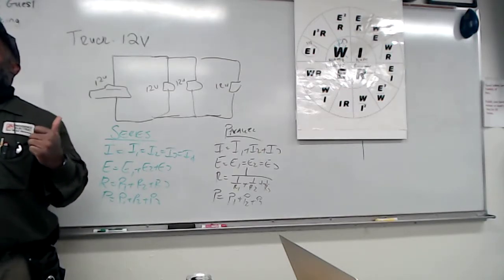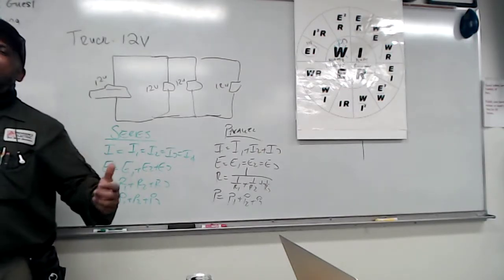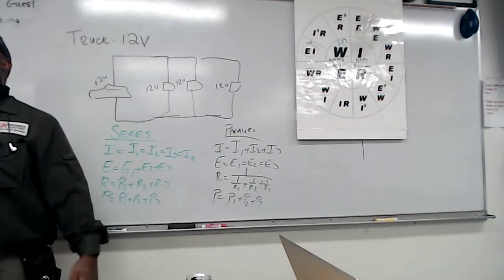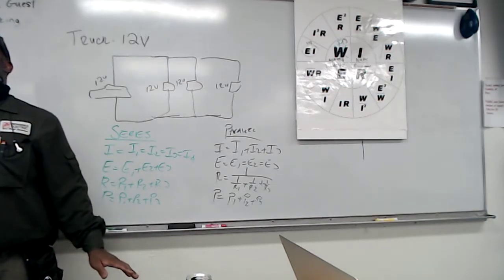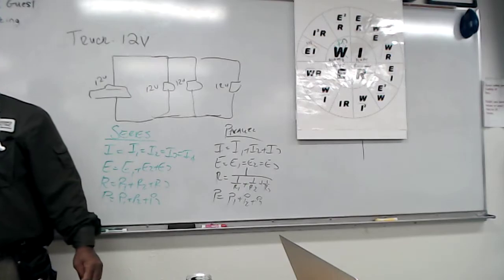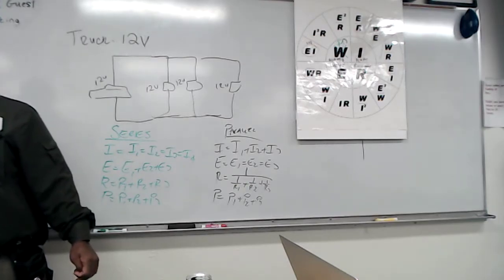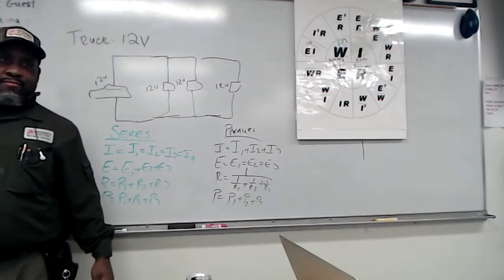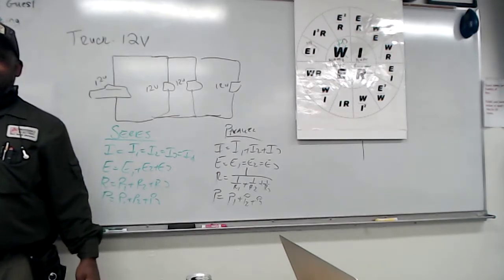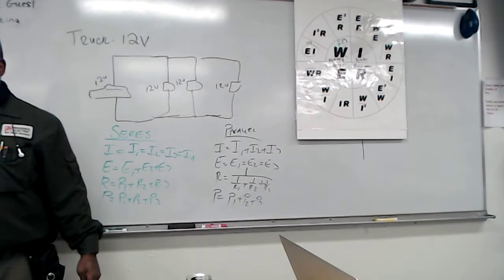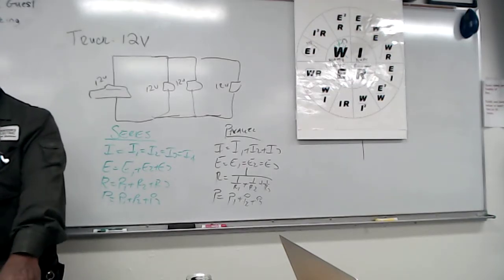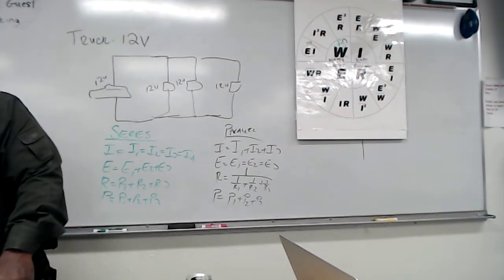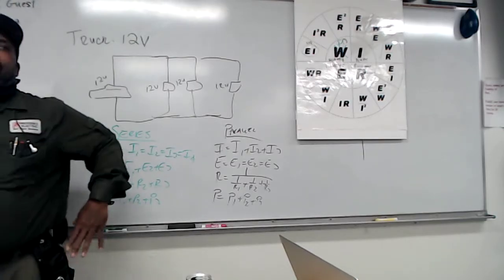Now, what column do we use for correction factors all the time, every day, and on weekends? What column is that, Madison? But what column? For correction factors only. 90-degree column. Right? So we're going to find THHN, number 14, and that tells us that's what? 25 amps. Yes?